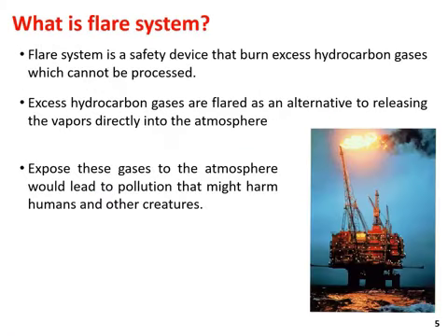Then again, what is a flare system? It's a safety device for when we have excess gas in the process, excess hydrocarbon gas. This is in the case of natural gas processing or refineries. So before we send it to the air, we will burn it in the flare and then we will send it to the air. Why do we do that?